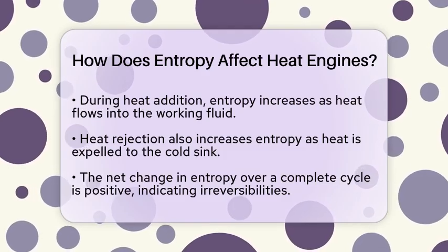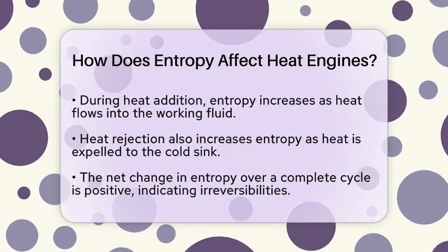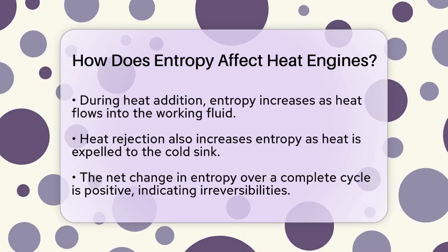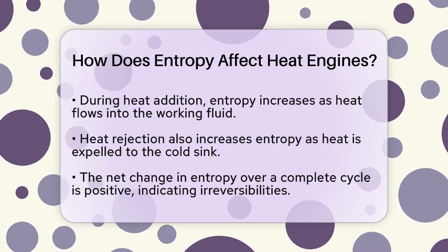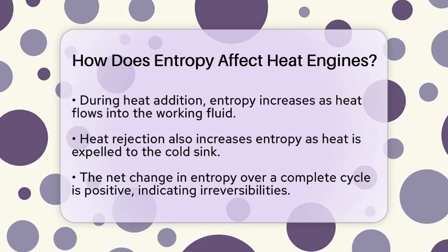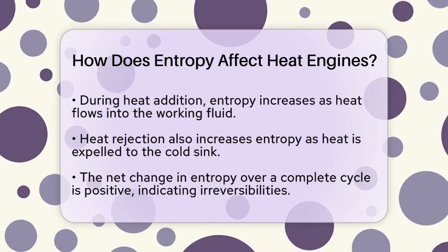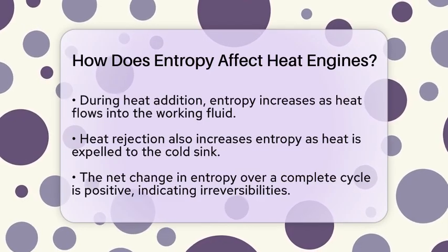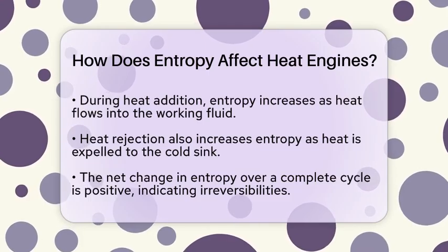Furthermore, some heat must always be rejected to the cold reservoir. This is necessary for the working fluid to return to its initial state, which is essential for maintaining a cyclic process. The disposal of the gained entropy during heat absorption is unavoidable.